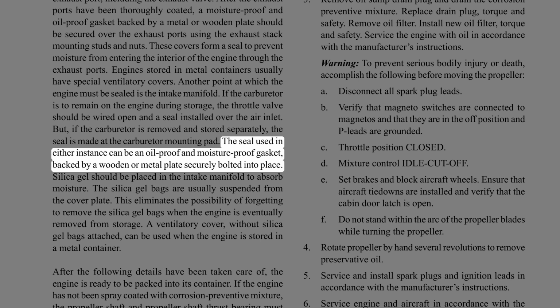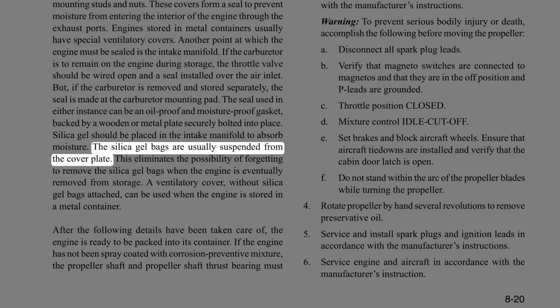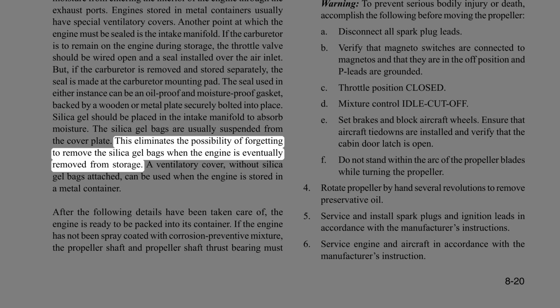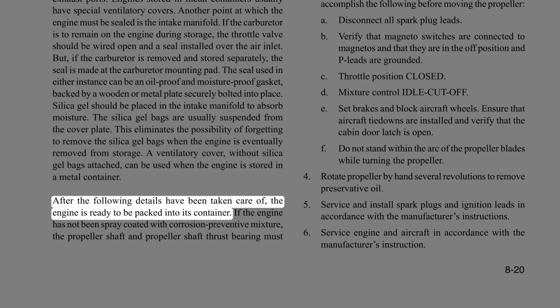securely bolted into place. Silica gel should be placed in the intake manifold to absorb moisture. The silica gel bags are usually suspended from the cover plate. This eliminates the possibility of forgetting to remove the silica gel bags when the engine is eventually removed from storage. A ventilatory cover, without silica gel bags attached, can be used when the engine is stored in a metal container. After the following details have been taken care of, the engine is ready to be packed into its container.